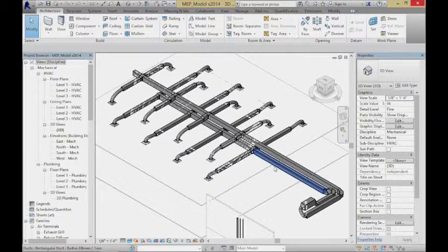So I'm supplying the air through a hard duct, but then rather than running a parallel system to pull the air away, I just say, there's a lot of airspace in here and there's a ceiling down here. What if I just pull through the entire ceiling and use the entire ceiling space as a big virtual duct? Okay, that's what we call a plenum.